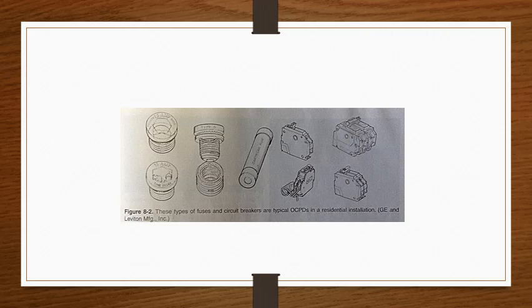Fuses. A fuse is a highly reliable and safe overcurrent device. It consists of a resistance-sensitive link encapsulated in a tube. The ends of the fuse are connected to contact terminals of the conductor. The link has very low resistance. If high current occurs, the link melts and opens the circuit.